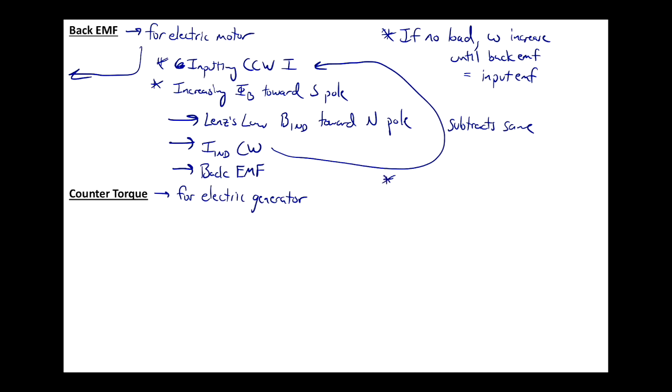No? Okay. So, if on the other hand there is a load, in other words, we're putting some mechanical resistance, if you want to think about it that way. Maybe it's a tire, okay? It's something that is actually having to turn. This will limit the angular velocity, so it's only going to be able to go so high because it's trying to actually turn something that has some mass and some weight, some moment of inertia, and that will keep the back EMF less than the input EMF.